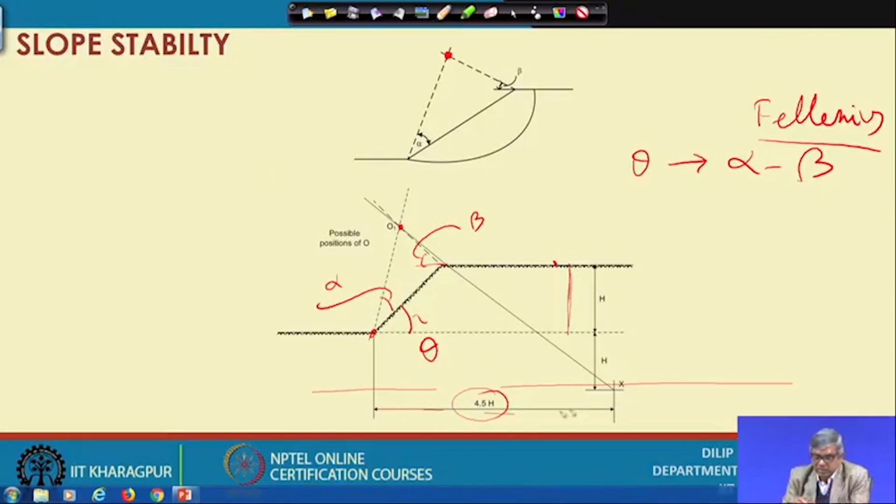This is the vertical line and this is the horizontal line, and they intersect at this point. This new point x is located, and finally joining this point x to the original center of the slip circle O1, and then after joining, you can extend it.